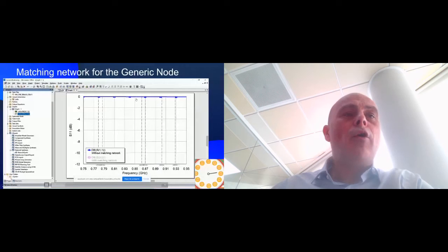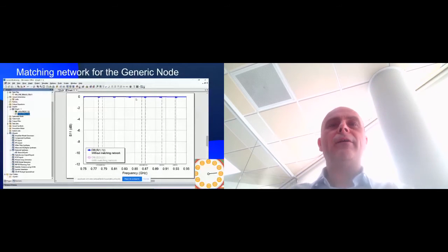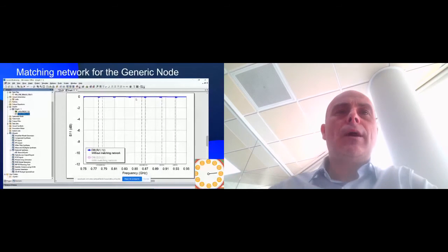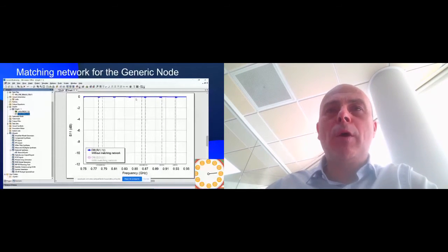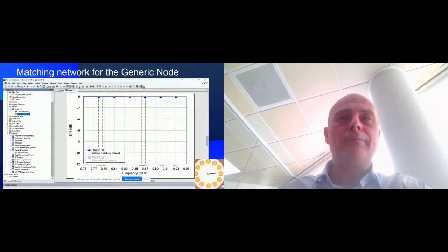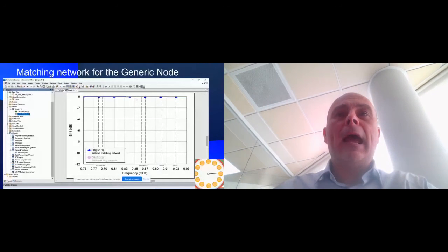And we are going to synthesize a matching network. We go to the network synthesis tool. We specify a wide frequency range. Also, we can choose components. How many components do we want? We say maximum 4. If there is a solution with 3 or 2, the software will tell us. Also, we can say, well, inductor and capacitor up to this value, no more than 50 nanos. So it's quite practical. And the goals.